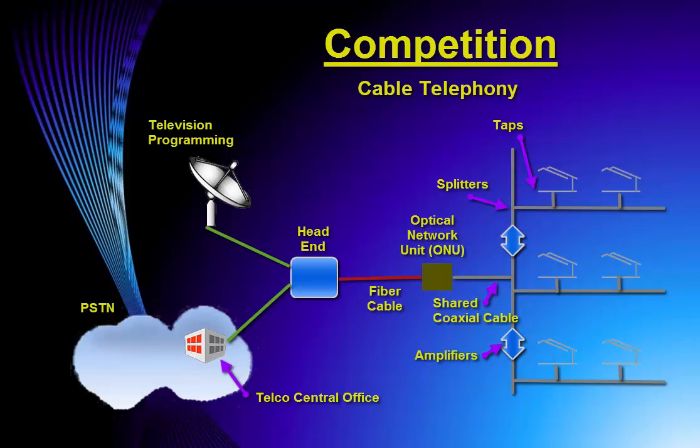Recently, the cable TV industry has changed the unidirectional amplifiers to bidirectional amplifiers in their network to allow for bidirectional services such as internet and voice over coaxial cable. Cable companies install fiber out into the coaxial network to an interface with the coaxial line at an optical network node, or ONU. Coaxial cable then provides the distribution to subscribers. This approach is called hybrid fiber coaxial cable, or HFC network. The internet service uses Ethernet to send internet signals over this arrangement on the coaxial cable. Subscribers share the capacity with their neighbors.